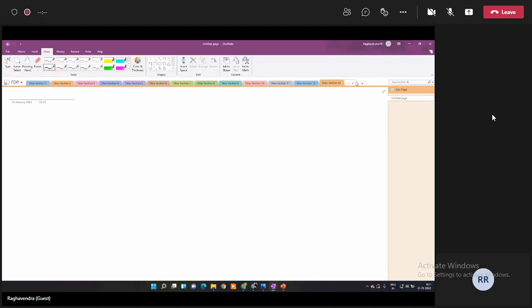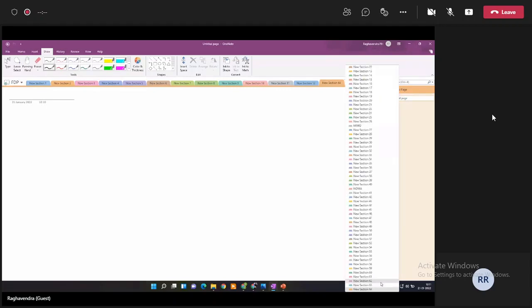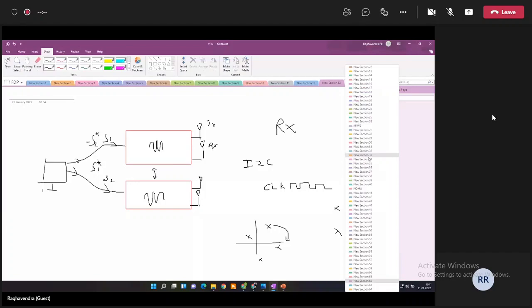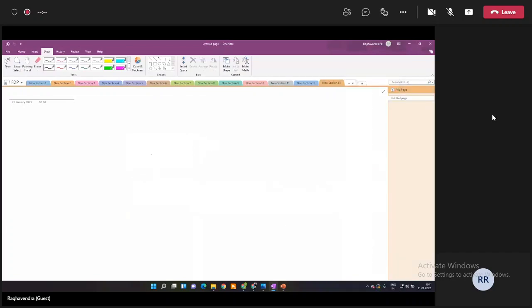So in order to get around this, let's say I'm taking a Rio also, but I want to do an 8x8 and not a 4x4 or a 2x2. That time I have no choice but to have multiple USRPs. But because of this problem where you have different clocks and different references in each USRP, you are not able to get a system that is very accurate. So what NI has done is they have made a product called an Octo Clock.